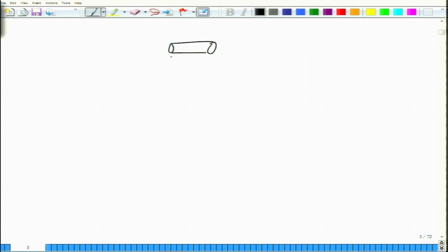While the forward pump drops down, is it possible for us to use a secondary pump in the backward direction, while the forward pump starts off initially very strong and then eventually falls off? What if we could have another pump in the backward direction, which would start off strongly here and then go down as it goes, eventually creating a kind of overall gain? It is possible for us to do so. This is called a co-propagating pump, and this of course is called a counter propagating pump.